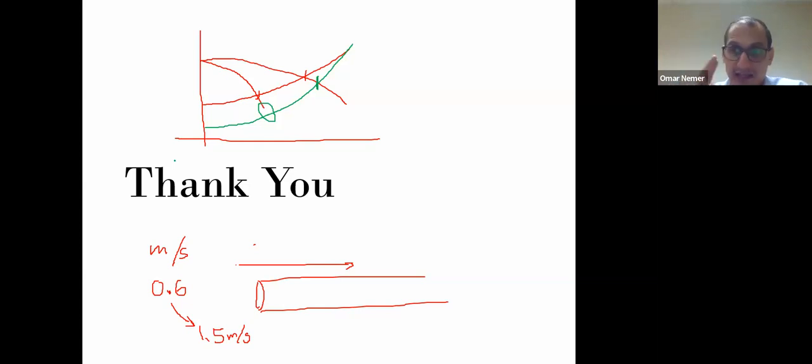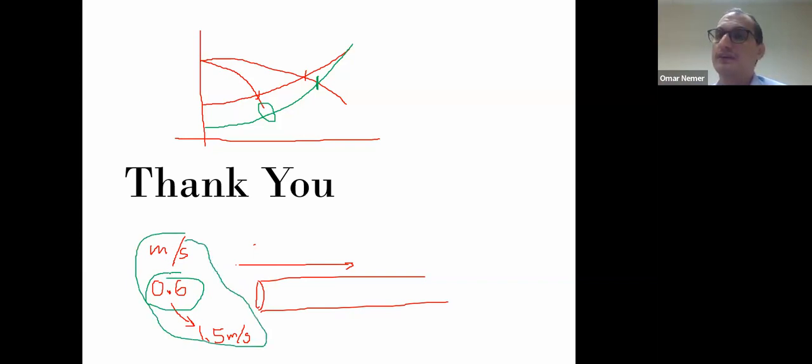So again, for single or dual pumps working together, if the sizing cares about this speed limit of the sewage, not less than 0.6, and it's not preferred to go higher than 1.5, we are okay with this pipe sizing.